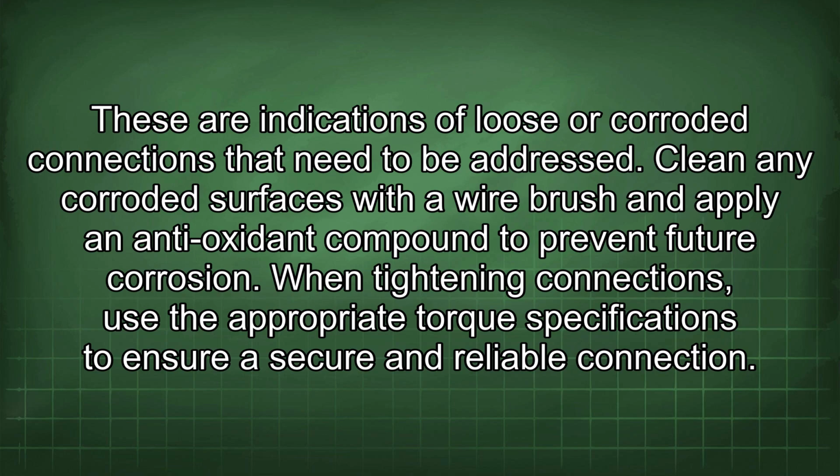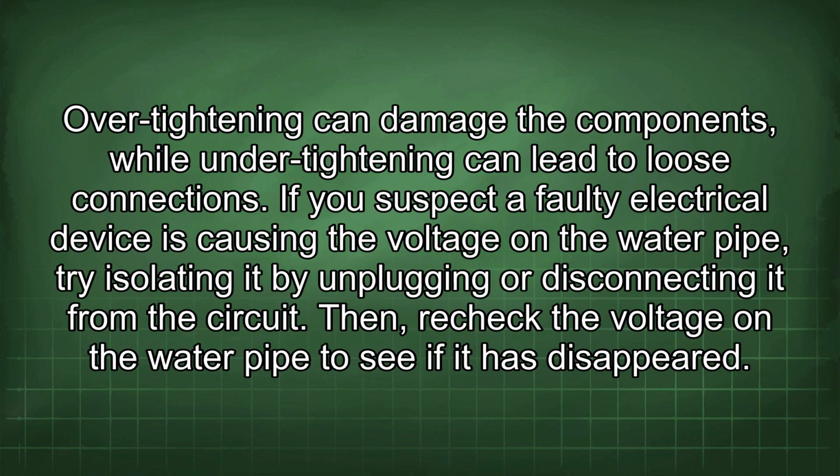When tightening connections, use the appropriate torque specifications to ensure a secure and reliable connection. Over-tightening can damage the components, while under-tightening can lead to loose connections.